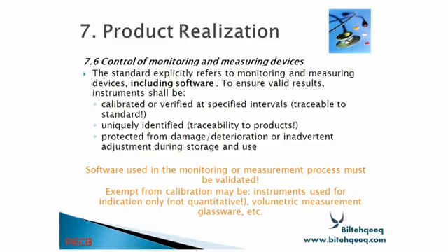Instruments shall be calibrated or verified at specific intervals, traceable to standards, uniquely identified for traceability to products, and protected from damage, deterioration, or inadvertent adjustment during storage and use. Software used in monitoring or measurement processes must be validated.